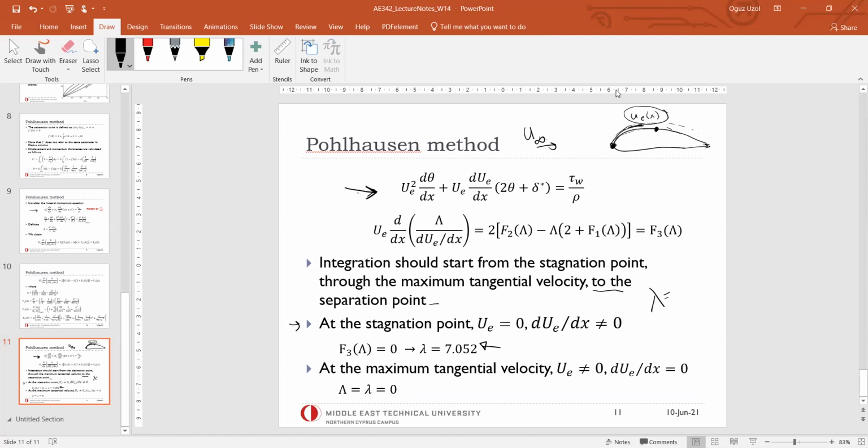Of course, the boundary layers that we're dealing with over more realistic surfaces, and in most real life applications, are most of the time not only laminar. They are laminar at some part. Let's say if this is the stagnation point of the airfoil, it will remain a laminar boundary layer until some part, and then in most cases transitions into a turbulent boundary layer.